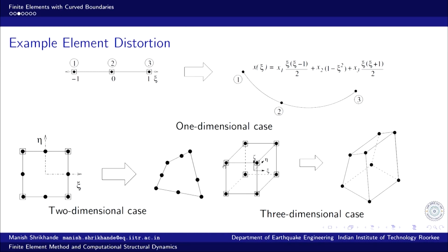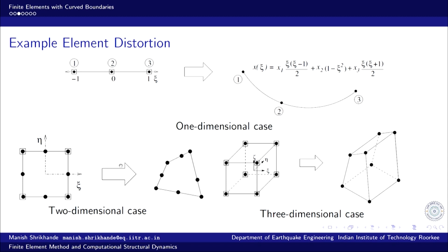For example, if I try to map this point here and this point here, that would actually go like this. So, this point gets mapped like this. So, there would be an overlap, right. Similarly, I can possibly try to map this such that this edge folds back onto the element itself. So, that would lose one to one correspondence, and there are mathematical indications of that happening.